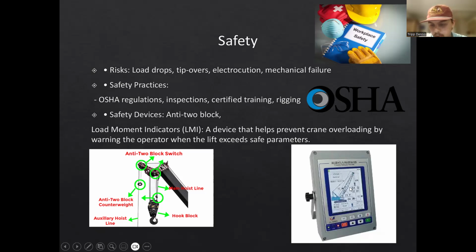That just tells the crane operator when he's picking up too much because he's extended way too far out for how heavy the load is. So he may have to move the crane back or something and get that load under a certain percentage of the crane's ability to lift.